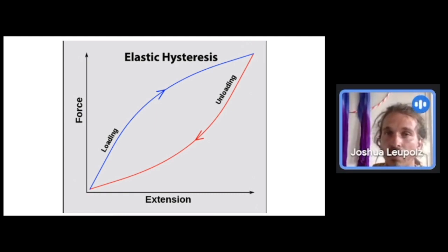But overall, I think if there was the possibility to look at these curves, you might get a better understanding of how your webbing behaves before you buy it, and you know exactly. Maybe if we start having these curves, we can see, okay, this webbing has a lot of losses, so it might be quite easy to walk because it feels like it's absorbing everything. And on other webbings, this area is relatively small, so if I start bouncing, the bounce will go on and I don't need to push much into it. So that could be quite interesting.